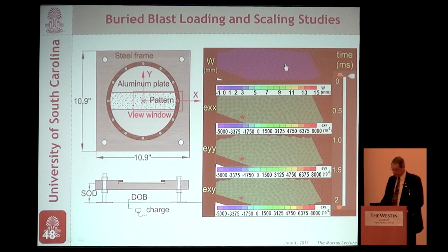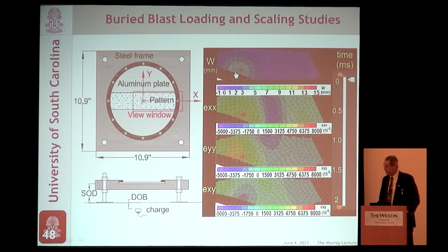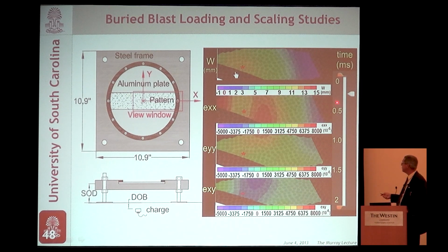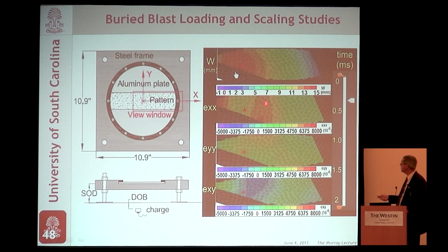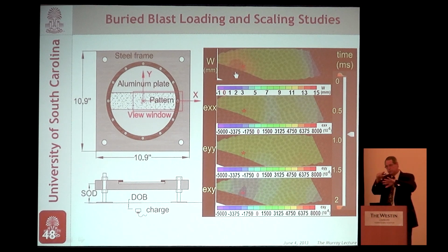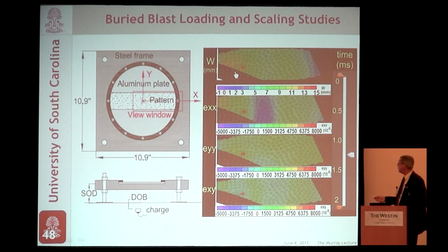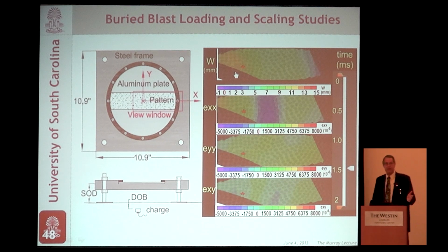From there, I want to look at the strain fields. Here they are. Here's the strain field in the X direction. Notice this large compressive region propagating all the way to the boundary, and then coming back with a rather large tensile region here. At the same time, the shear strains and the epsilon YY, which is the hoop strain, are not symmetric. That would be consistent with the way it actually was deforming, because it was deforming in a symmetric manner, so that the deformations in this direction would be different. Eventually, it led to a compressive region here at the base of one of those waves that slowly faded out over time. So you can see the kind of rich data you can get.